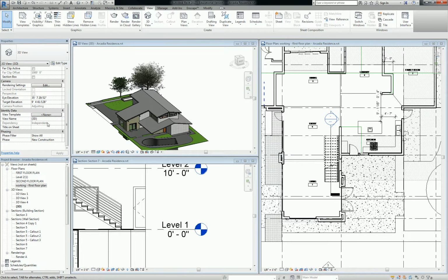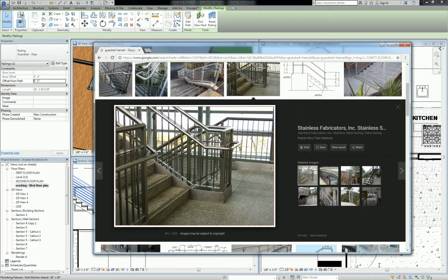Awesome. So here's the rail, right? So part of the problem here is when you take a Revit railing and you try to extend it, because particularly in commercial applications, a railing needs to have an extension at the bottom, at the end of the bottom tread. So let's just go into Revit and do what the intuitive move is, which is to say I'm going to edit the path and I'm going to extend it by an extra foot or so. Right? I'm hyper extending it here a little bit, right? So I'm going to hit check, and we'll take a look at what it does.